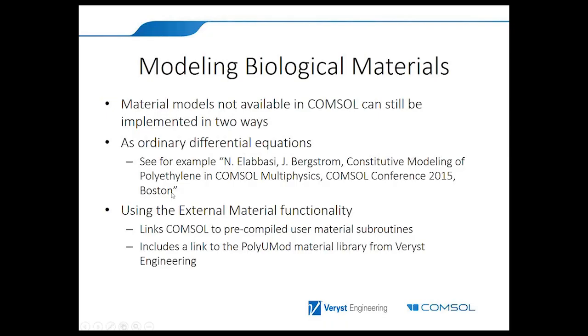The other option is to use the external material functionality, a new functionality introduced in 5.2, which allows COMSOL to link to pre-compiled user material libraries, whether structural or electromagnetic or whatever. In this case, we are using it to link to PolyUMod, a material library that we developed here at Veryst, with material models explicitly made for rubber, biological tissues, and plastics.